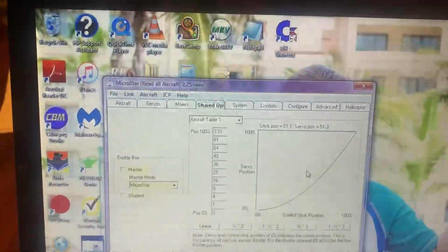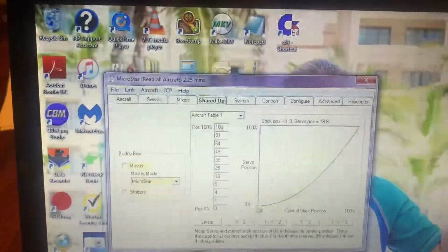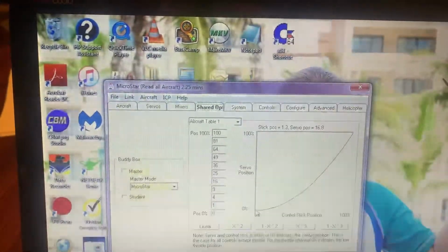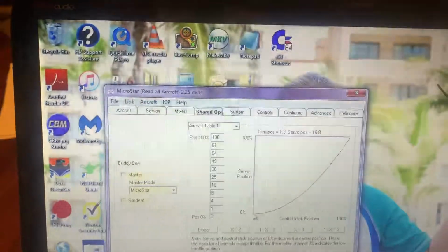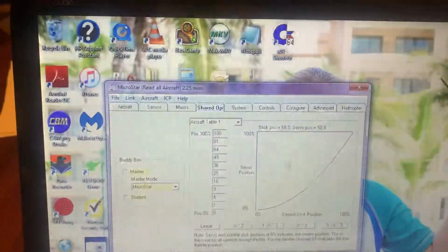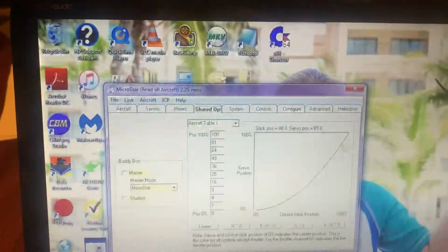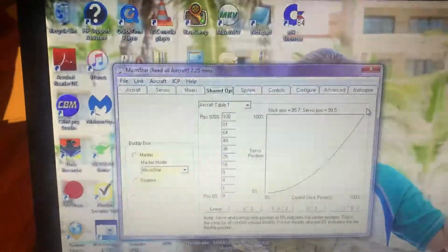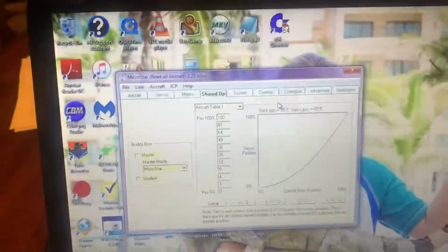Halfway is 0, and then down at low stick is, again, 100% negative pitch, so it may be 8 or 10 degrees negative pitch. So you can set independent throttle and pitch curves for each of 4 different helicopter flight modes, as I'll show you in just a second.